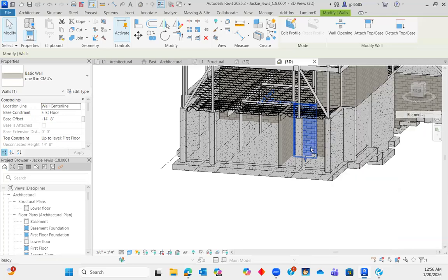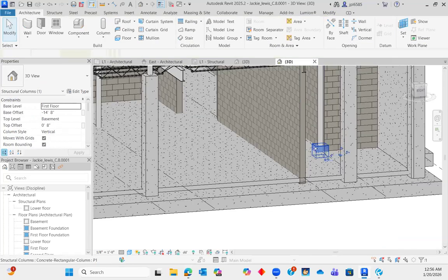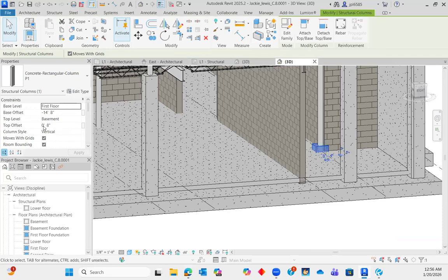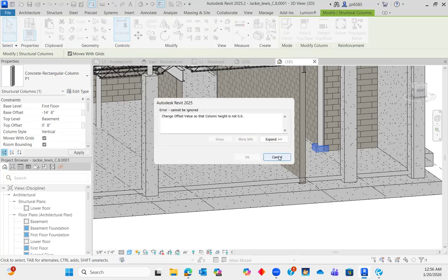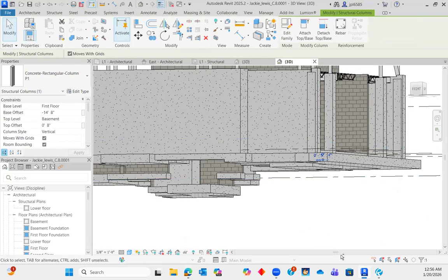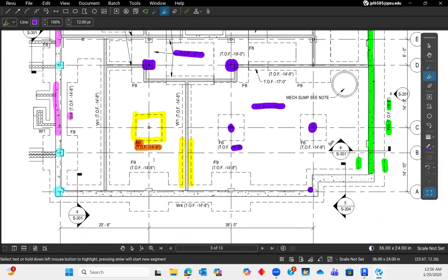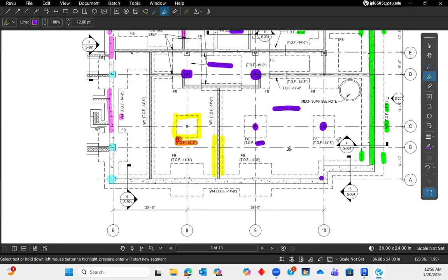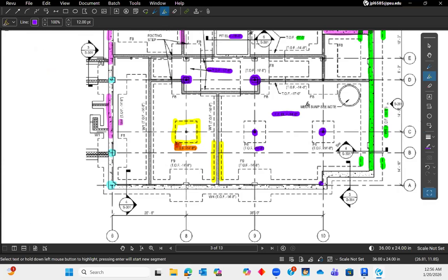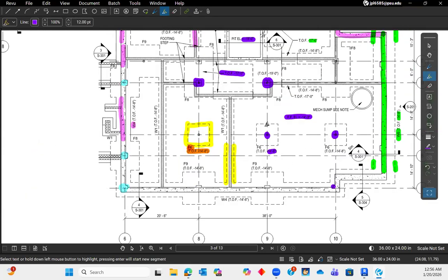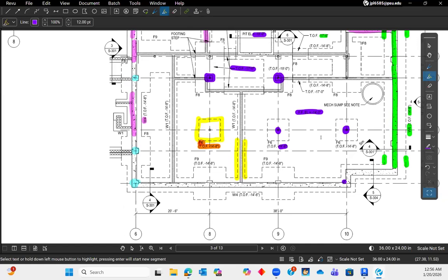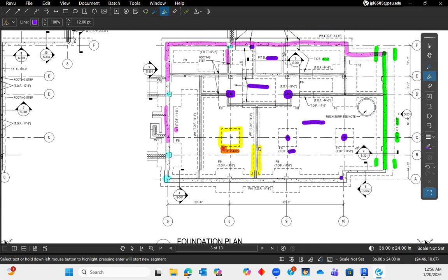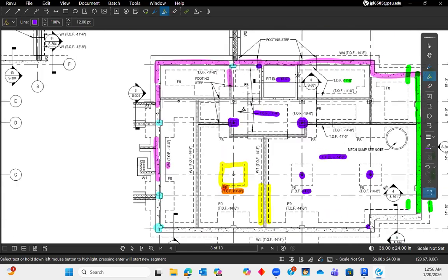let's see. Here's a good example. That's actually supposed to be -8 inches, so it is wrong. Oh yeah, they actually end up being 0 at some of these. Like this one, the pier is non-existent because 8 inches below is exactly where the elevation is, and you have to take into account the thickness of this slab on grade. So for some of these, the pier is really the basement slab on grade. But for others, it could be different.